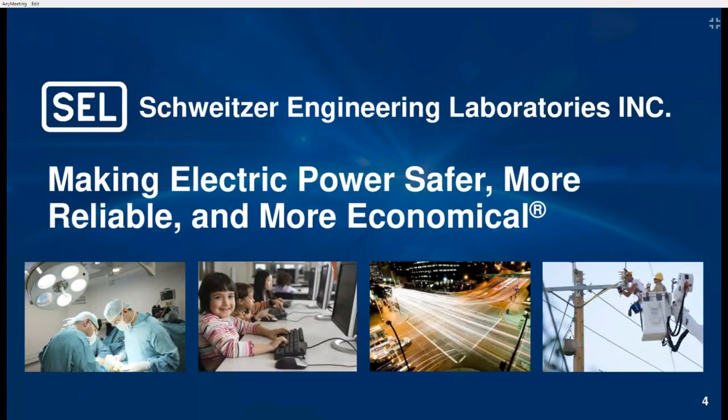Now, with Ed's device, it did several things. One, it contained a distance element that allowed you to figure out where that break happened, so that you would instantly know within about 100 to 300 meters where the break happened, so you could go out and restore power faster. And then not only did it do the fault location, it also recorded why that decision was made so that the utility could determine root cause of the event and then fix that problem so it didn't happen again. And since that time, we've continually identified, measured, and improved our devices over time.